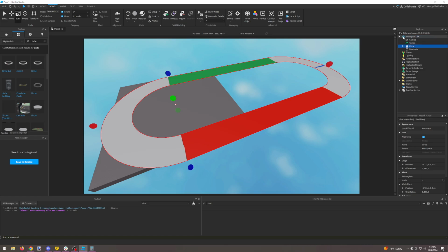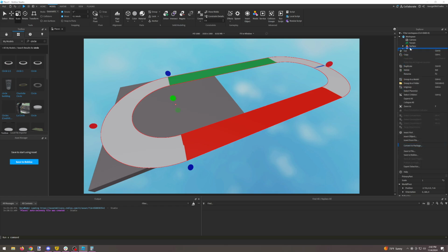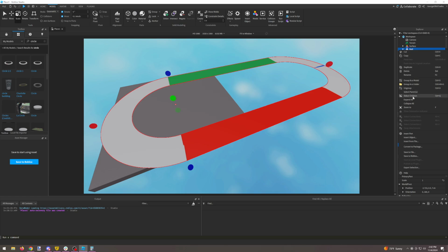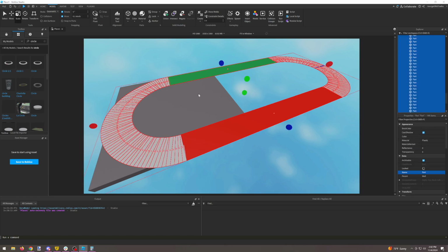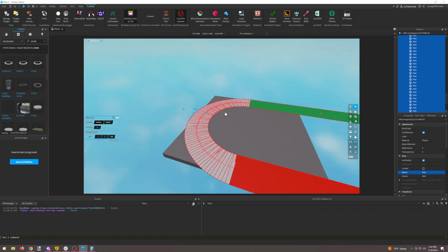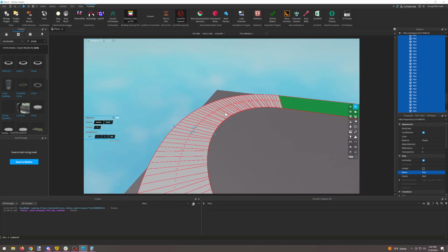Next thing that we want to do, so this is our surface. Next thing we want to do is build out our walls. So we duplicate, that's Control D while selecting over the surface. And this one will be our walls. And select the children. So that's right click, select children. I also have it set up as Control Q, but I believe that's not a preset hotkey. Could be wrong, but you should just check by doing the right click.